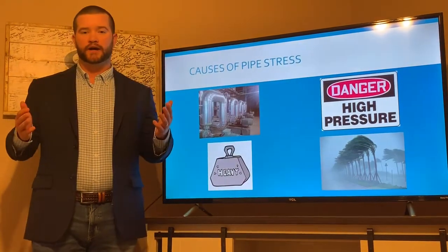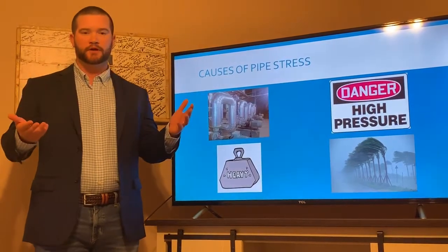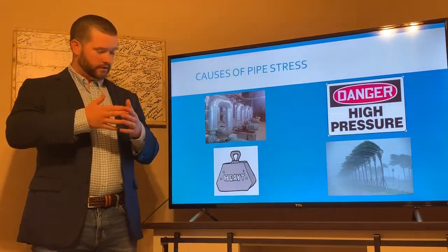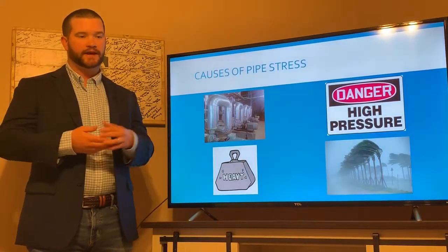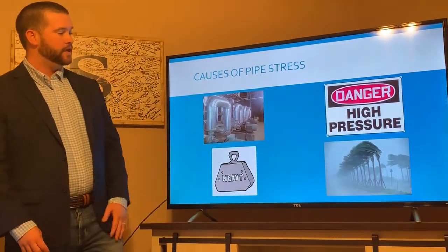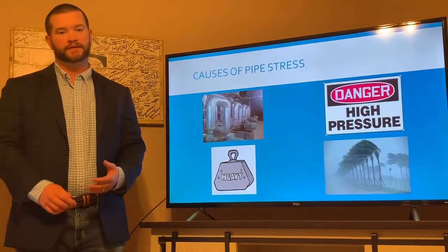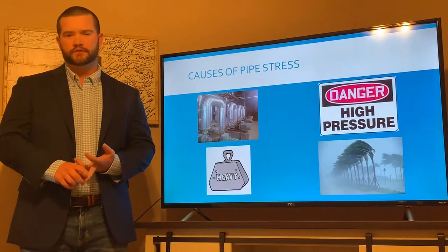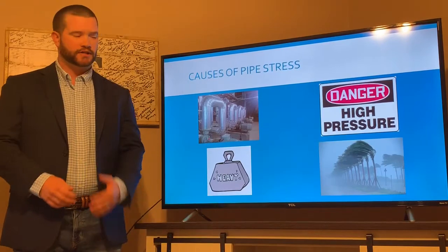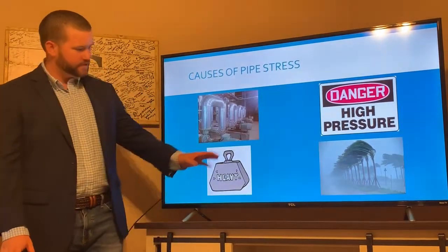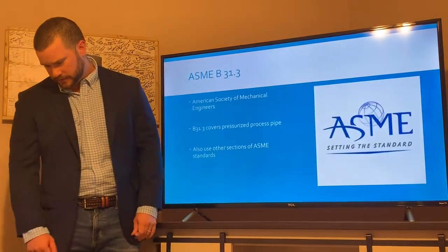If you have a long run of pipe that spans too great a distance, we've all seen a moment and shear diagram. The long distance is going to cause a bending moment in the pipe, and that could cause stress that's greater than is allowed. And then you also have occasional factors that lead to pipe stress, such as wind. There's earthquake codes in the ASME codes, and then mechanical vibration and things like that. Wind is the largest occasional factor that plays into pipe stress.